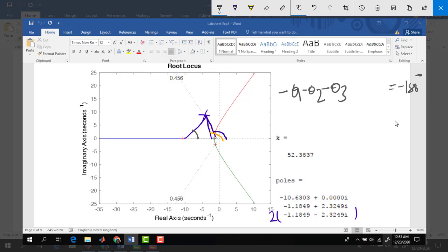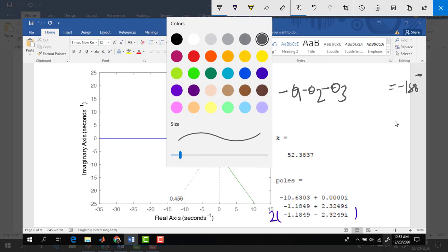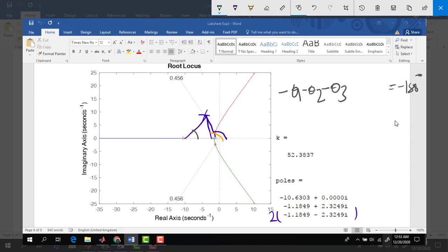We have a liberty to choose either the zero or the pole. There are all poles here, so for the simplicity of the calculation, let's say we are placing the new zero at s equal to minus 2. How will this save our lives or make our lives easier? So there is a pole and a zero at the same point.